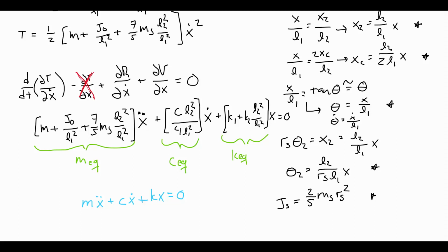So the whole purpose of this modeling work was, well, the end result is getting this equation of motion. Looking at this equation of motion, I know from the 0 it's autonomous, or it's a free system. There is an x dot term, so it's damped, and it has an x dot and x double dot. It's linear, and it's second order.